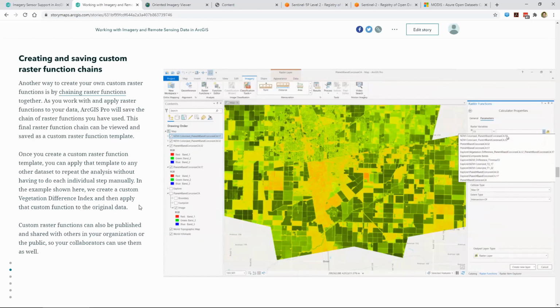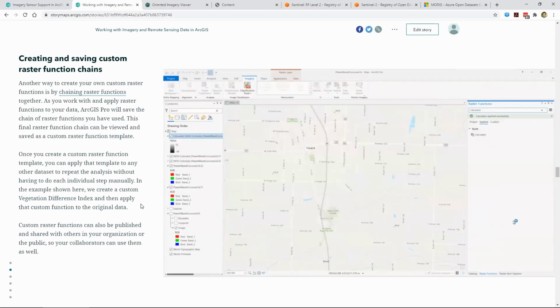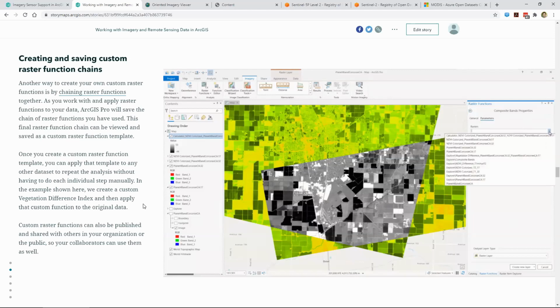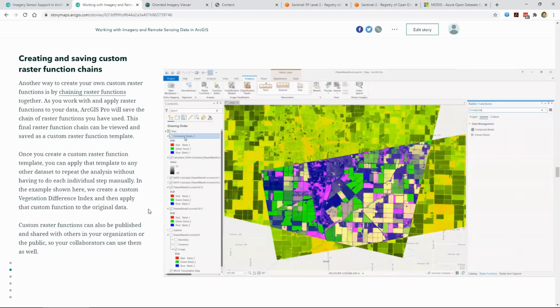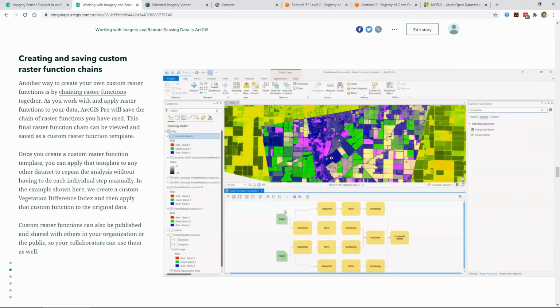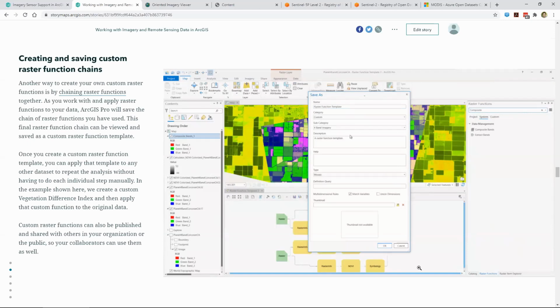And so here we're using a raster function called the raster calculator, and we're just identifying what those variables are for each one of those images. So we've got a T1 and a T2, and then we're just going to do an expression where we subtract T1 from T2. And so what that does is it gives us a change layer based on NDVI values. And then we can take that and composite this into a 3-band product. And then we can apply a color map on top of that. And so really the point of this is just to highlight where that change has been. So the magenta colors represent where there's been a decrease in vegetation, and green represents where there's been an increase in vegetation.